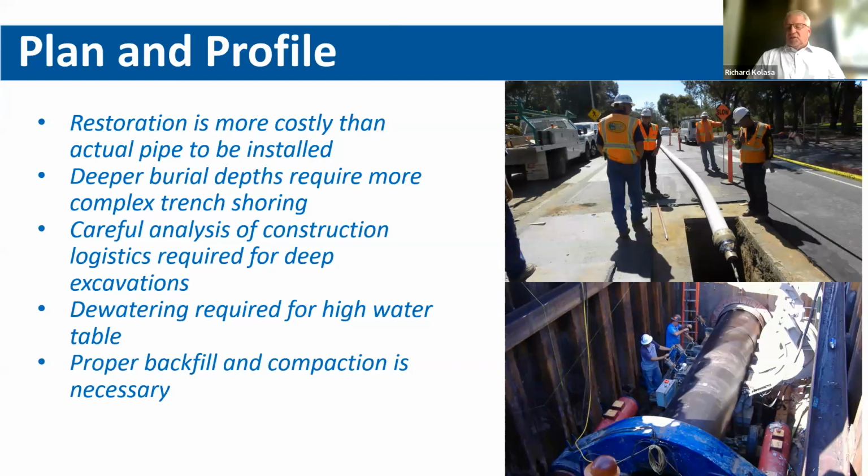Yeah, one of the things that I saw in the transition from segmented pipe or bell and spigot installations, even on open trench, versus polyethylene, is that a lot of the inexperienced contractors would lay the pipe along that whole system like they would a bell and spigot system. Whereas for the polyethylene, you can make the train in one location and then just pull that string into place to where it has to go, like that drill or that pull, or even laying it down or laying it right across the top. You don't have to move the equipment, so that actually saves a lot of time.